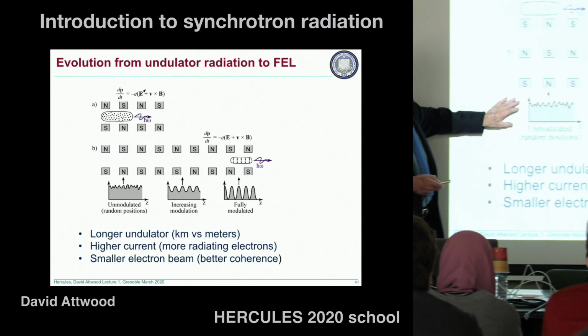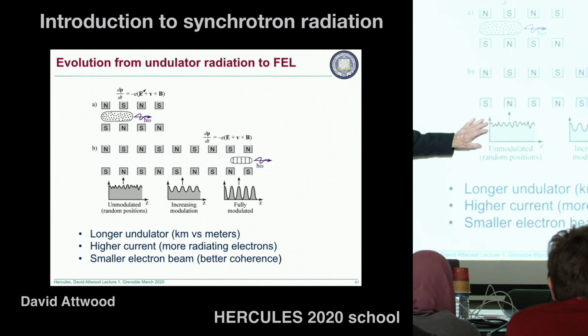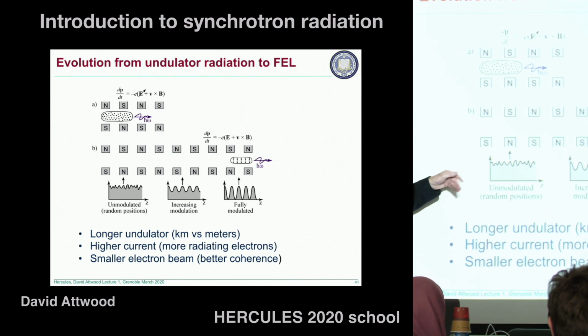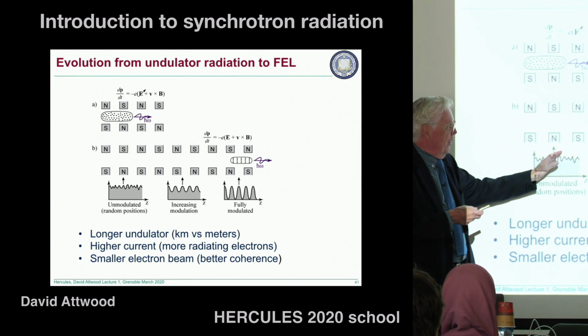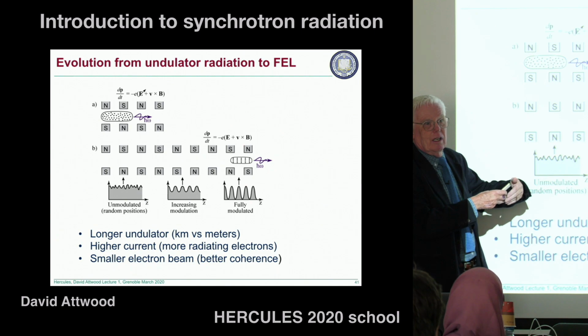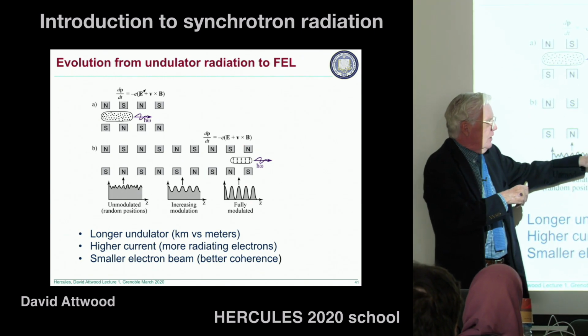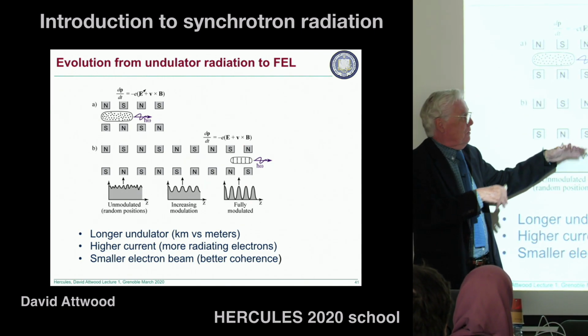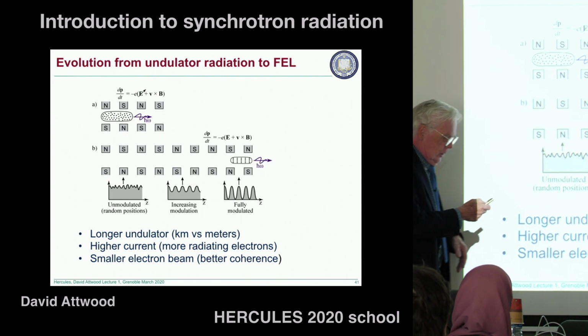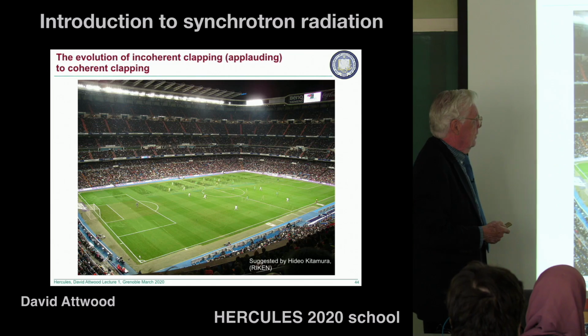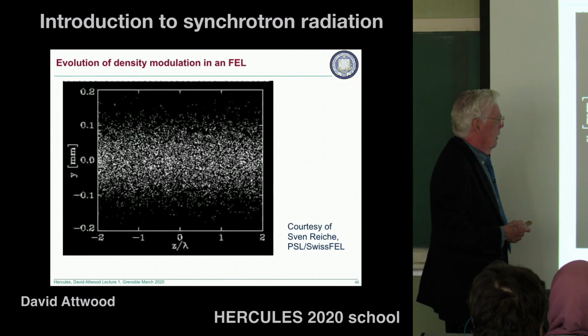So you're in the beginning, it's just a small effect of this crossing. The electric field is causing a little bit of bunching, but that increases the electric field. So as it moves along further, the electric field is stronger. The bunching, the modulation starts to get stronger, so the electric field. So now you have an exponential growth, okay, which then brings us to a slide.